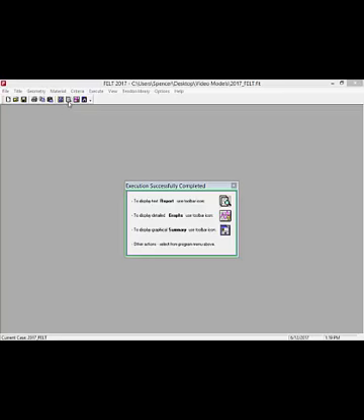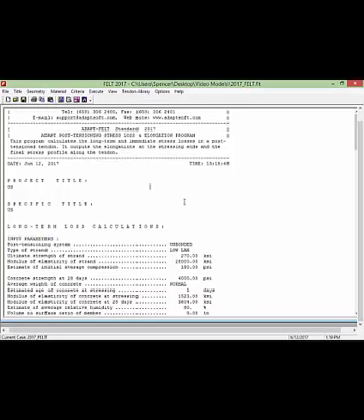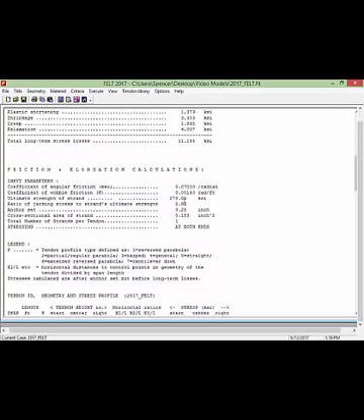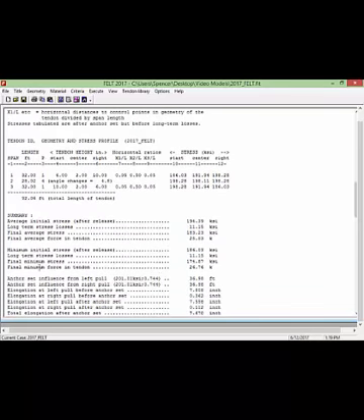In the output, if we select the Detailed Report option and navigate down to the stress output, we can see now that there's a block which contains the minimum initial stress, long-term stress losses, final minimum stress, and final minimum force in the tendon related to the minimum stress. This is in addition to the average values shown above in the summary.